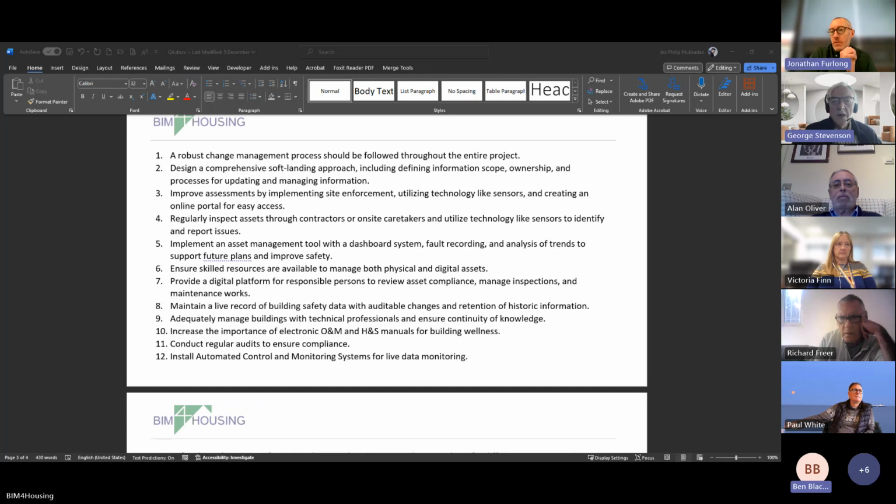Absolutely, yeah. There's no point in having drawings in your golden thread that don't show what you've built. I completely agree, but in theory, a building shouldn't get signed off at Gateway 3 unless that information is correct. Now, it may not. There's a separate question of whether all the information that's signed off at Gateway 3 is the information that somebody needs to operate a building. For instance, some people were talking about the information going out of date, and I think that's a different question, because you can have enough design information to pass Gateway 3 and hand over a building.